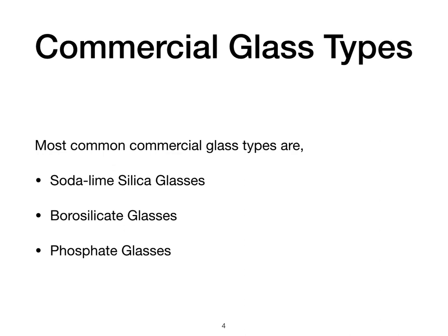While many glasses may quickly degrade in abrasive environments, borosilicate glasses have shown an ability to stand up to the task. They are commonly used in lighting applications where surface degradation and loss of transmitted light are undesirable. They are also commonly used for laboratory glassware, sight glass within industrial equipment, transformer bushings, explosion-proof lightings, and exterior aircraft lenses.